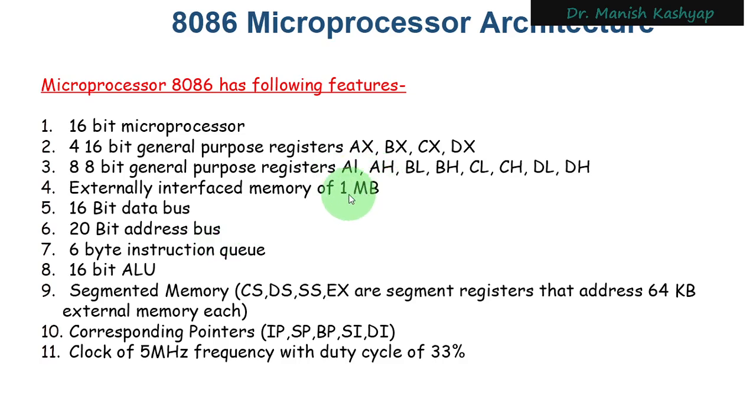1 mega stands for the total number of locations that will be there in memory, and byte stands for the fact that every location is of 1 byte, that means 8 bits. So we have 1 megabyte storage, which is external storage, and this external storage is divided into four sections: extra segment, code segment, then you have data segment, and then you have stack segment, right?